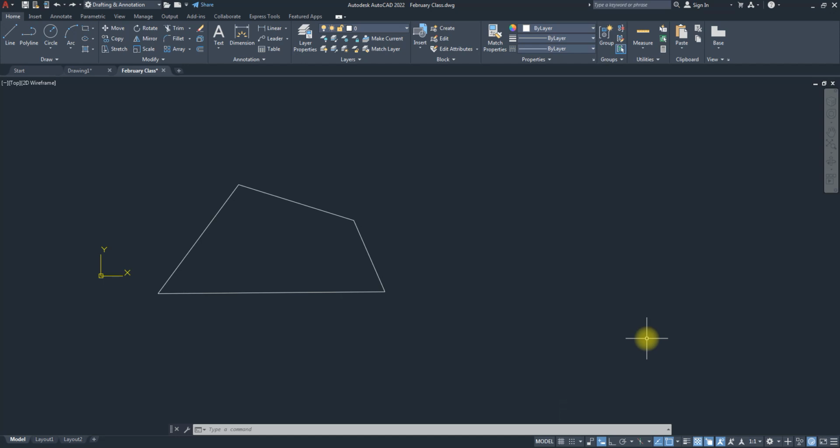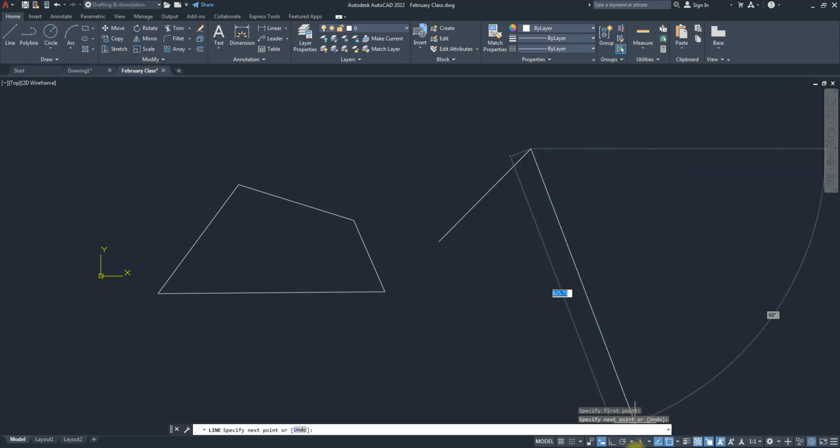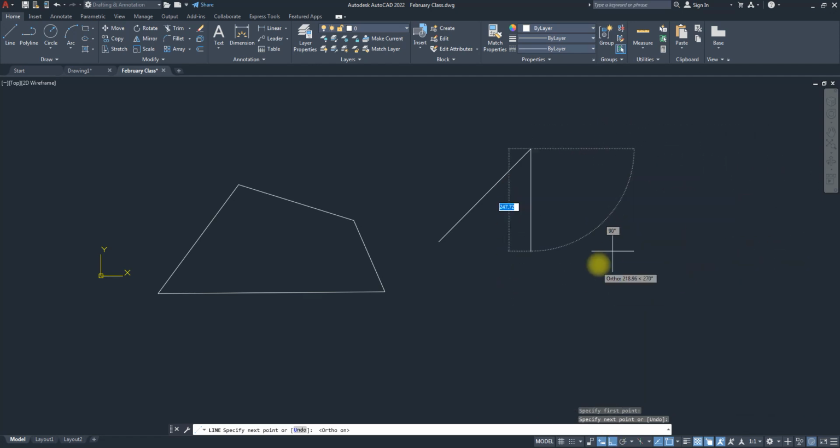Do you understand? So talking about that line, for me to make my line vertically and horizontally straight, just to constrain it, I have to turn on a mode option, which is this Auto mode. If I turn it on, look at what happens. I told you that anytime these things have blue highlights, that means they are in the on state. If the blue highlight goes away, they are in the off state. So right now, this perpendicular icon is in the off state. If I click on this, it's in the on state, you can see. I'm unable to go freely now. I can only go either horizontal or vertical. All right? So that's that.